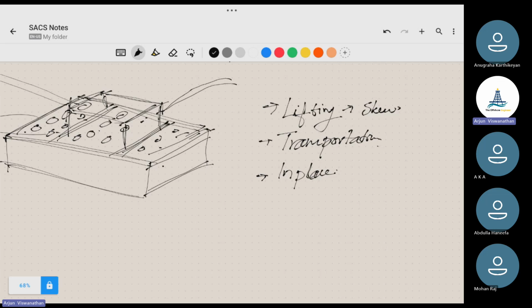Then in place means we will take the structure and go to the seabed. So in the seabed, what are the external loads that can act on the structure? Here, most of the time, it will be just due to water depth, and some currents may be coming, because waves will not affect it at that depth; it will be very deep. That also, but we have certain external loads coming into it. That is very critical in the in-place analysis for subsea structures.